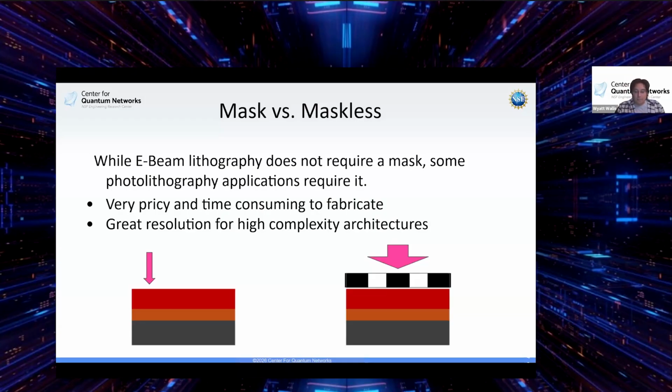Okay. So this would be the difference between mask versus maskless. When you're thinking about what resolution you want, having a photomask usually can give you a slightly better resolution. And so if you have the photomask on hand, it might be worth doing that. That is, yet again, it all goes back to what materials you are using, what photoresist, and so on and so forth.